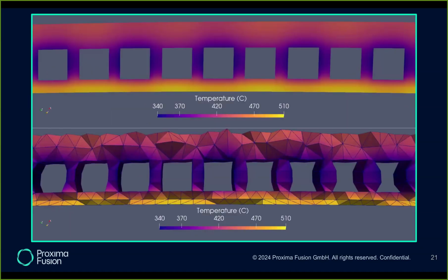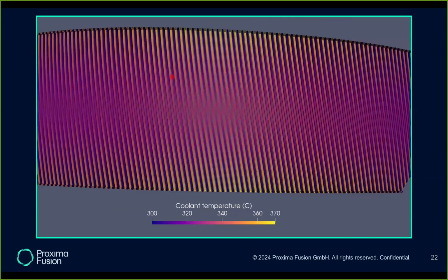If we slice it, we can see very nicely the distinction here, with the boundary between the tungsten and the Eurofer, which have two different thermal conductivities. You can see that this section here is close to an inlet of a pipe. This one is close to an outlet because temperature is lower here, higher here. And if you look now at the outlet temperature of the pipes, which is very important because it's what lets you extract energy from the machine in part, then we see that we have an increase in the temperature of the pipes that goes up to about 70 degrees. And this is very important because this is consistent with what we see in the literature for tokamaks or other similar machines.